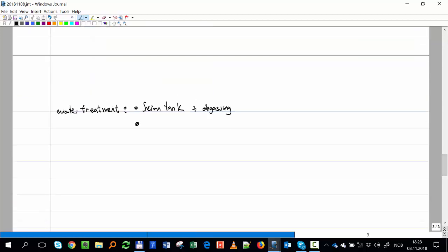But on a platform, this is very typical onshore. On platforms, we don't have that much space to put a big tank of water. So we use hydrocyclones. In hydrocyclones, we use very high Gs, very high rotation of the fluid, and that makes the heaviest fluid, the water, separate and go to the walls, and the oil stays in the center.